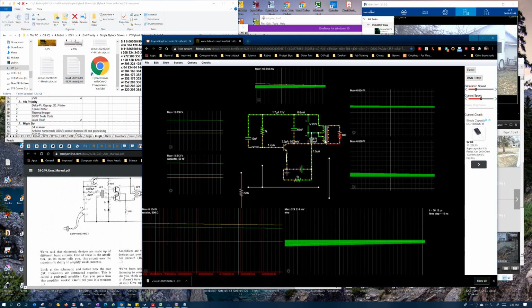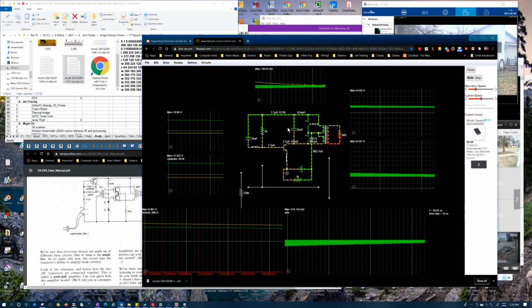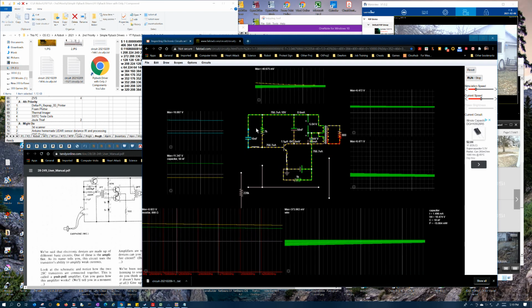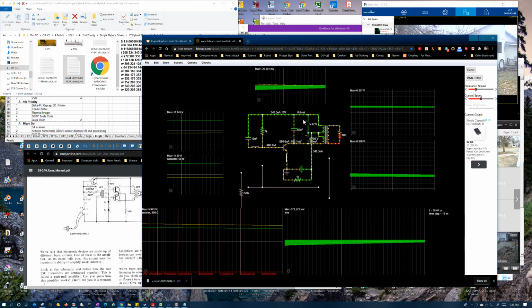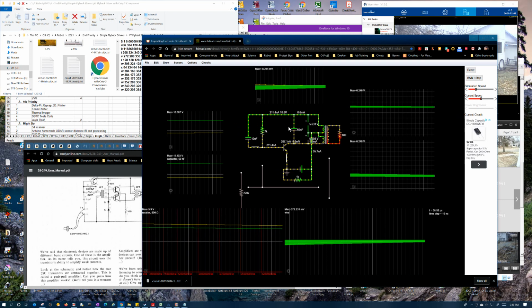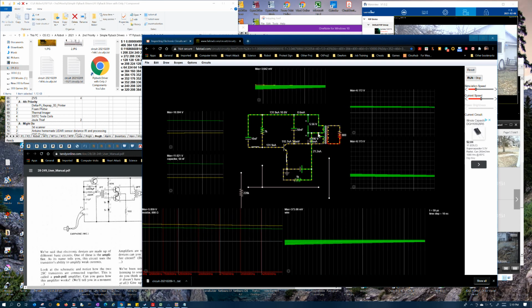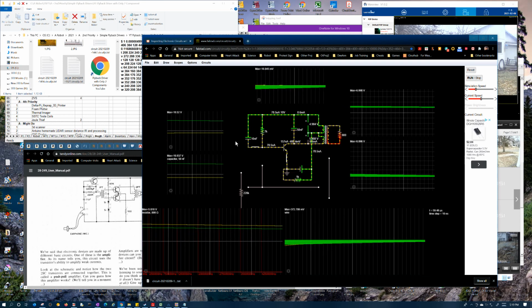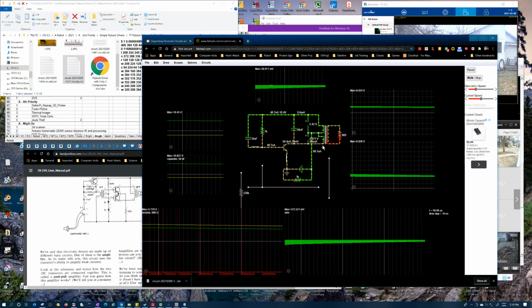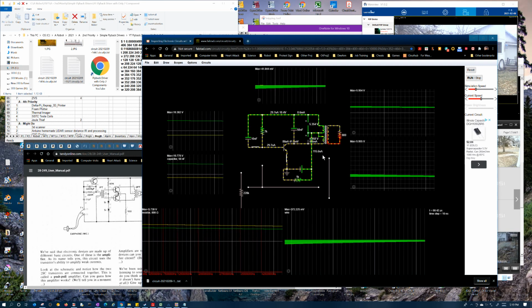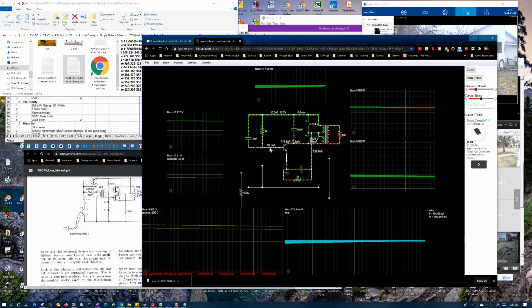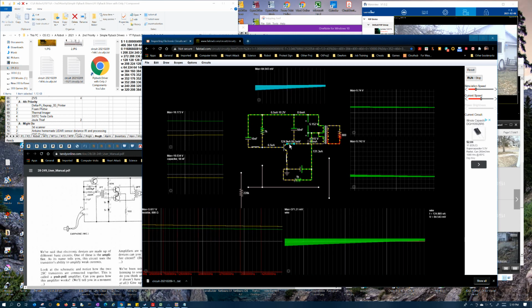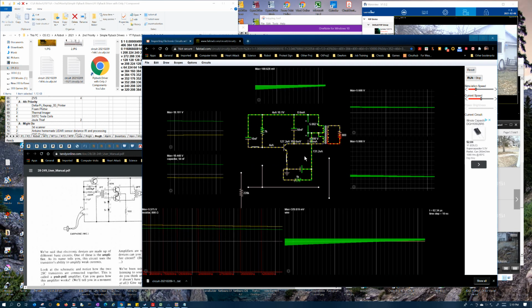But I was wondering, as this collapses, what's discharging these capacitors? In theory, it's probably the field, right? It's about 10 volts across this. So in theory, this collapsing field is maybe trying to draw those capacitors down too. But it's still certainly keeping the transistor hard off, and that's nanoamps of current right there.